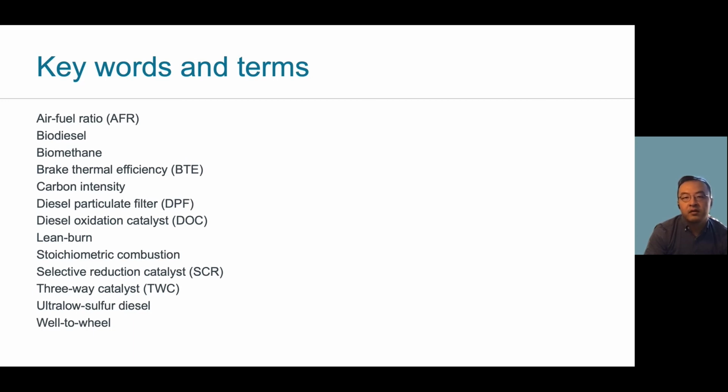Selective reduction catalyst is a diesel aftertreatment technology to convert NOx to water and nitrogen over a catalytic surface. A three-way catalyst is an aftertreatment system in gasoline and natural gas engines. It oxidizes hydrocarbons and carbon monoxide and reduces nitrogen oxides present in the exhaust gas.